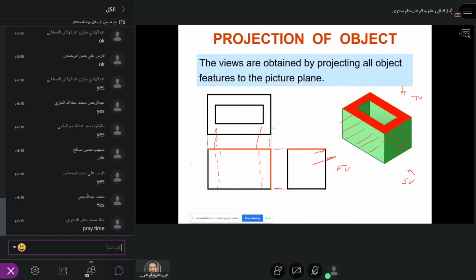And for the side view also, what I do, I project this line, okay, then I draw a 45-degree angle and then project back here and then I draw this line. So now I see the front view, I can identify, okay, I can see actually a solid surface, but there is something hidden here. Then I compare this with the top view, okay, there will be a rectangular section hidden and which is shown here. And the side view, yes, these two edges are hidden, so that edge is here. And this surface is what is shown here. So this is the way you can represent those hidden edges.